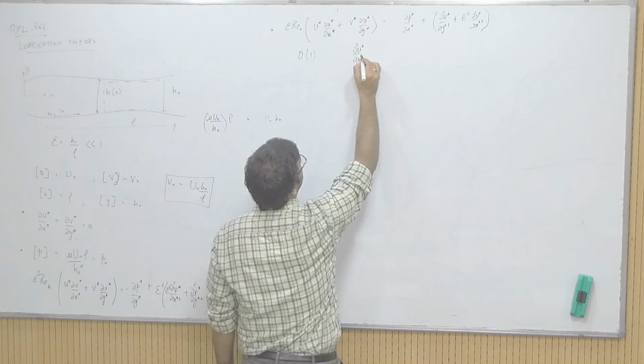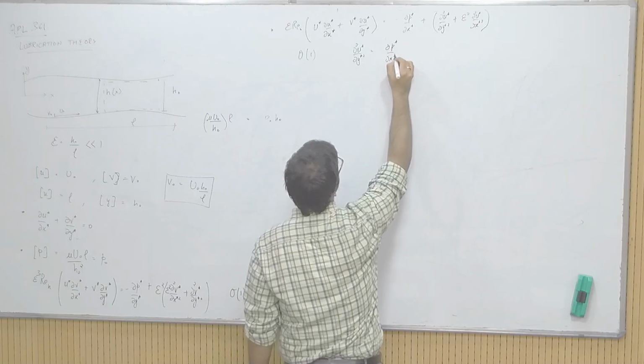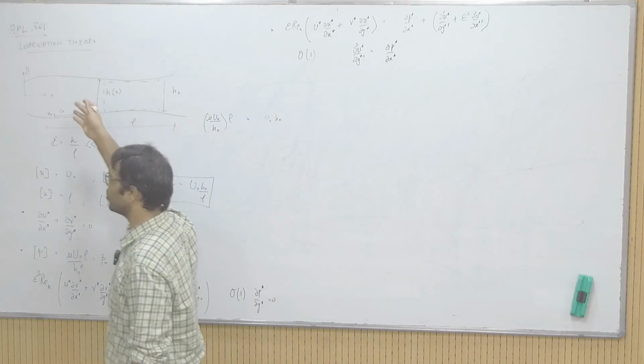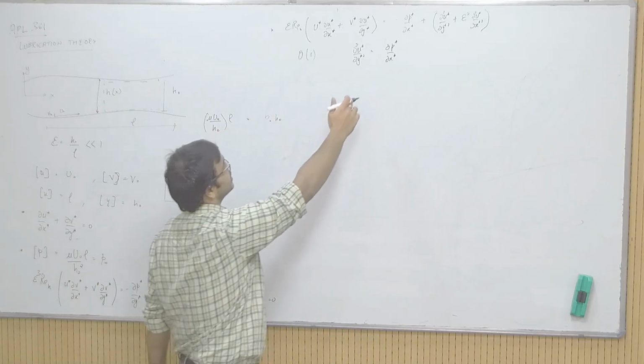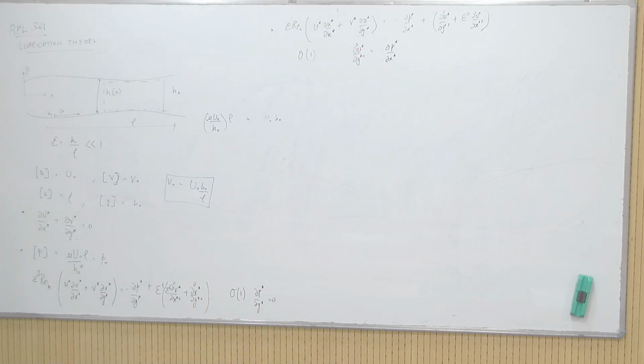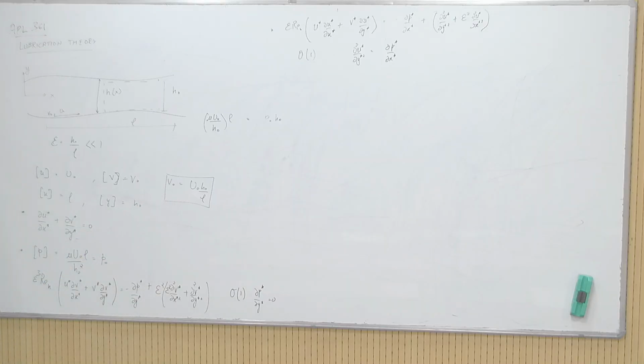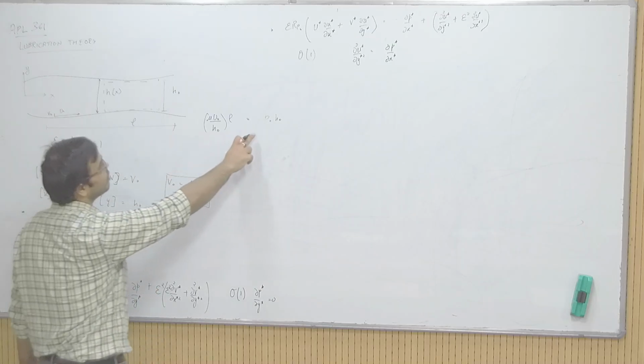But remember that even though the equation looks similar to your unidirectional flow in a channel, this velocity u star is not anymore just a function of y. This is not a unidirectional flow. You have a y velocity component in this flow. It is small, but it is there, in this analysis.